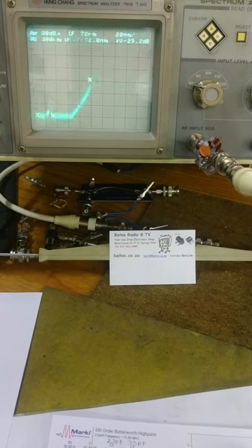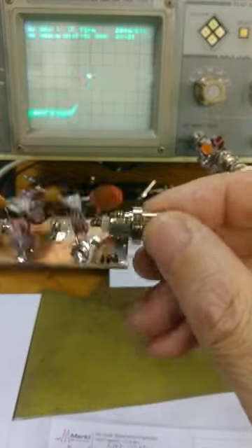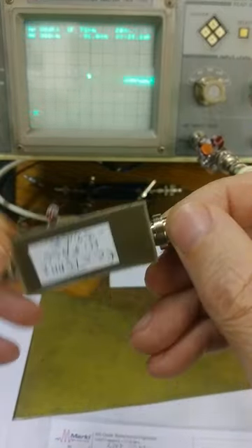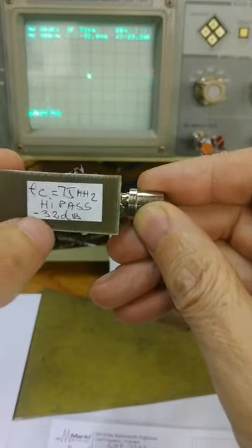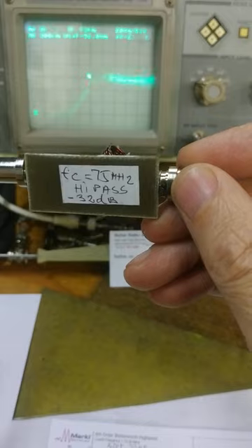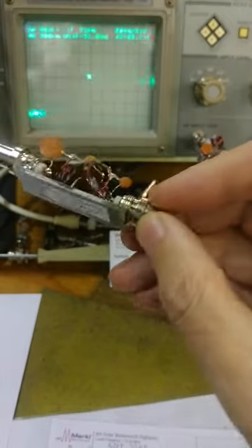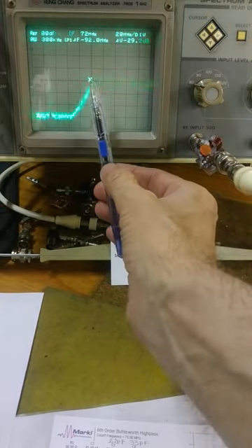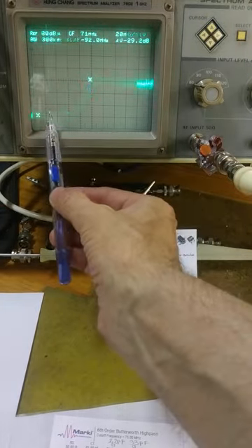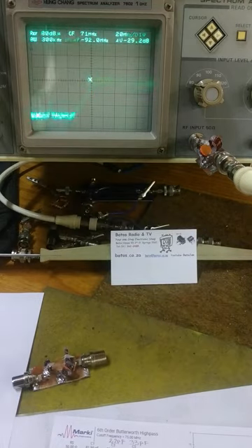So, as I said, on that note, we can make the filter into any order. I'm going to make these type of filters, FC75 high pass, minus 32 dB. The reason is because it gives me a 32 dB attenuation, which is about 1200 times attenuating all the signals from 75 down to 0, which is quite a decent attenuation.